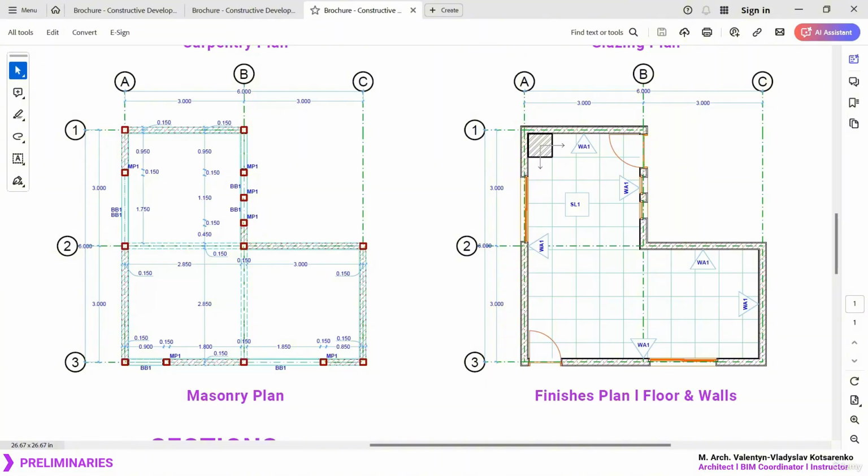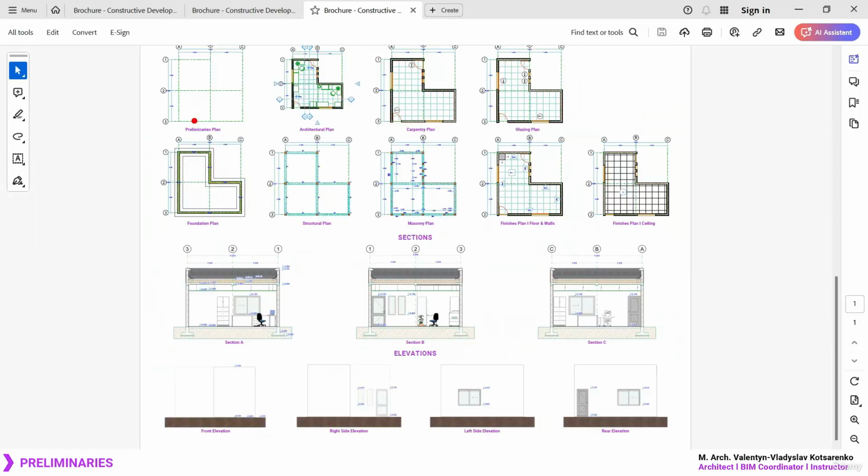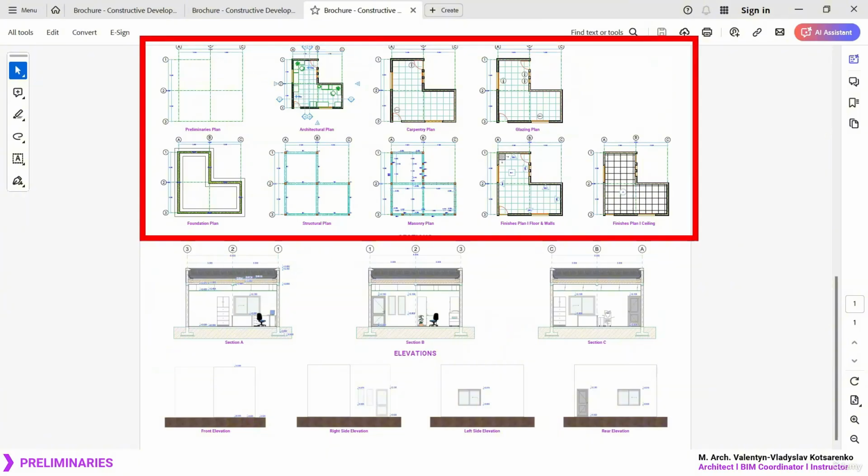In a similar way to what we already did in the previous course, Basic BIM Framework, where I explained that you can use the auto annotation commands or auto dimensioning functions, you simply select everything and ArchiCAD will dimension it for you. In this case, we're going to apply something similar. We are just going to focus on generating the different ground floors, because you can apply the same workflow to generate all types of views, sections, and elevations.